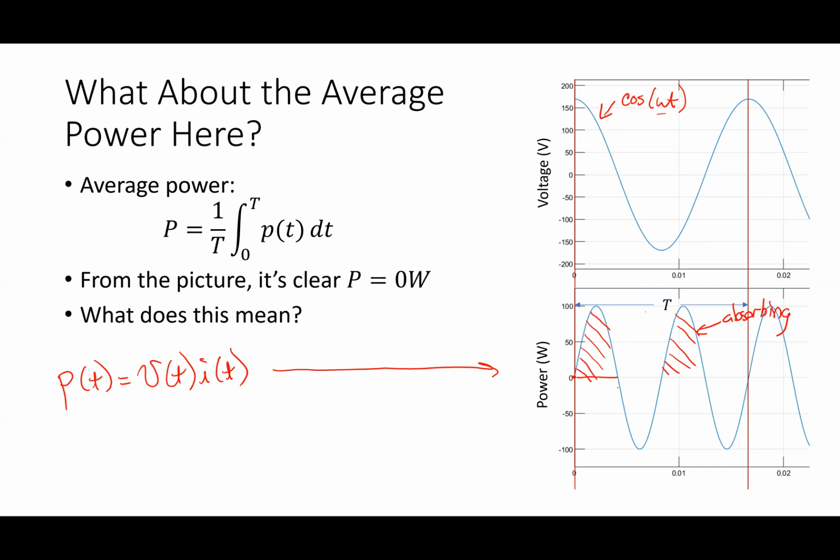right? And then down here is the opposite, right? He's supplying it or sourcing it. This is with the inductor. Yeah, and it wouldn't matter. It doesn't matter if it's an inductor or a capacitor. Why is that happening? What's true about the angle between the current and the voltage in that case? Well, they're 90 degrees apart. When they're 90 degrees apart, what ends up happening is that half the time energy is being absorbed, half the time energy is being sourced, right? Because this guy is an energy storage element, okay?